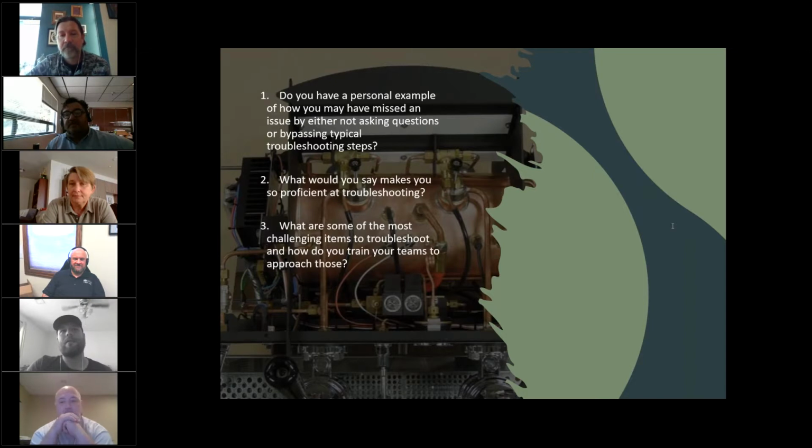Because even if you don't understand the mechanical side of things and how electrical impacts those things, it gets really complex really fast. So if you can do simple electrical tests with your meter, like adding a chassis connection, let's say you're working on a modular system and you should be getting voltage there, it starts to really reduce the location and you can start to isolate where those issues are.